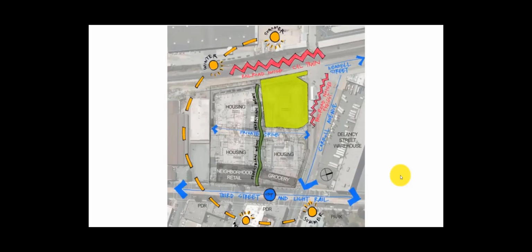Here's another way of establishing a site analysis. I've used this several times in class and in different offices that I've worked with, where you take an aerial photo and kind of gray it out and then add your graphics to it. So you want to really take a look at where the summer and the winter sun is and what the angle is. You want to be aware of all that sun that's coming in on the south side, any noise from the road, and kind of directions that are happening on the site. And you can see the graphics are dynamic in some of these.